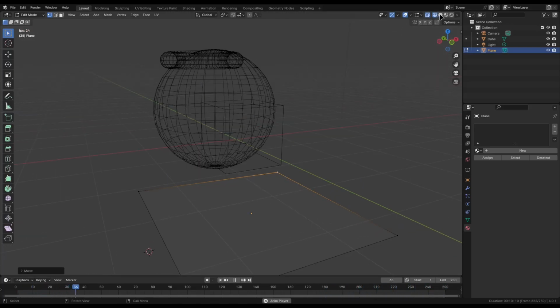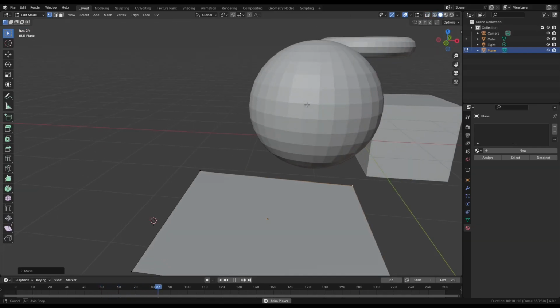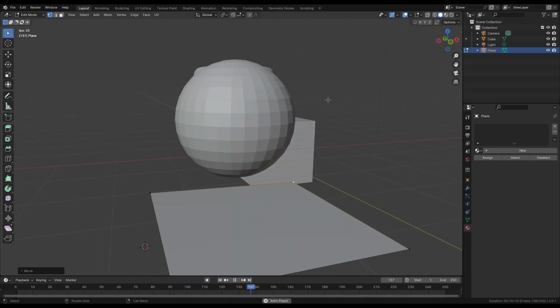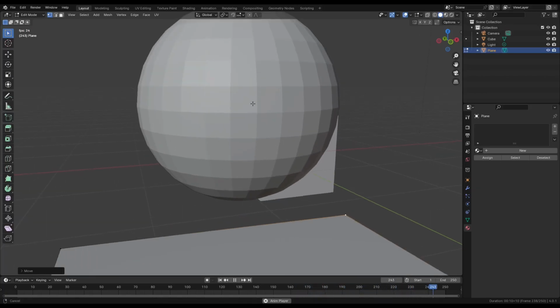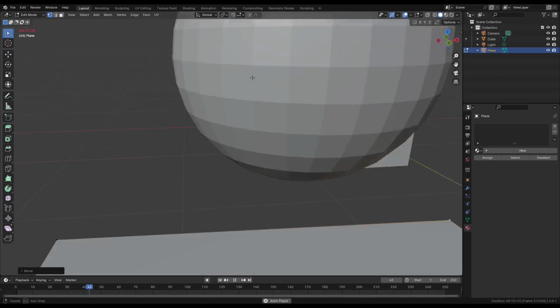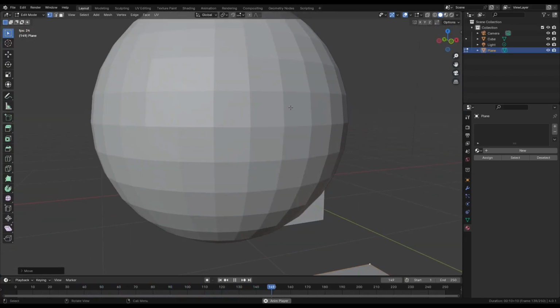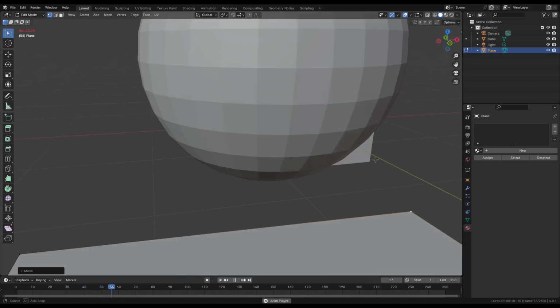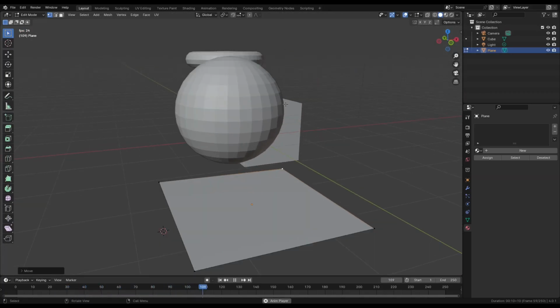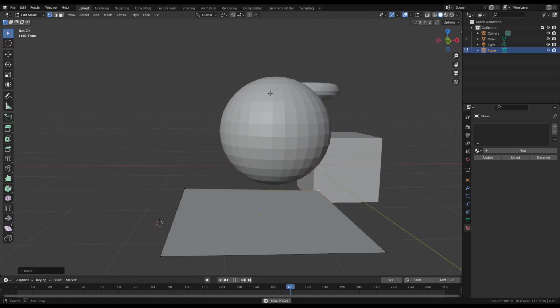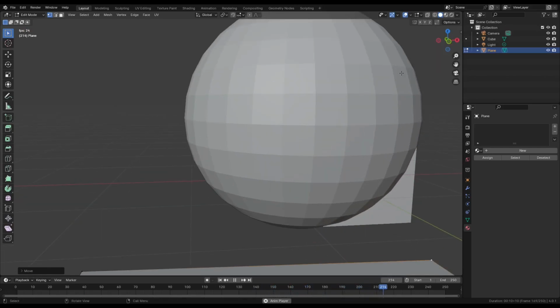And faces are used to build the actual surface of the object. They are what you see when you render the mesh. A face is defined as the area between either 3 vertices (triangles), 4 (quadrangles), or more (n-gons), with an edge on every side. The faces are often abbreviated to tris, quads, and n-gons. Triangles are always flat and therefore easy to calculate. On the other hand, quadrangles deform well and are therefore preferred for animation and subdivision modeling.